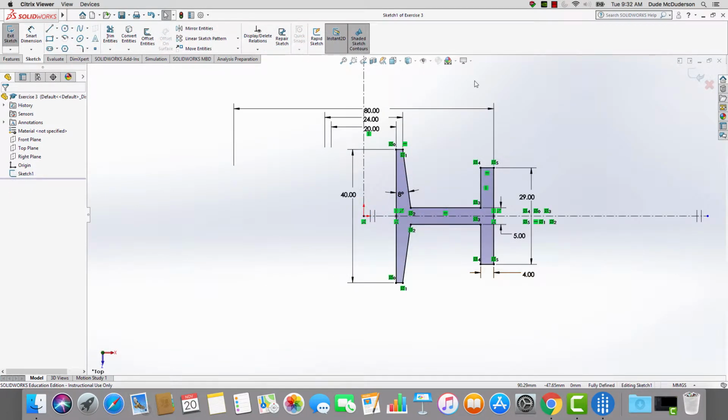So let's take a look at the sketch that underlies this revolve. Again, we're looking now at the cross section of the wheel, and we're looking at just one side of that cross section. Very much it looks just like this outside geometry that we've portrayed here. You'll note two other really important components here: the center line here, which is going to provide our axis of revolution, and we also have a center line here. This really speaks to efficiency in drawing. There's no reason to draw the entire thing when we can just draw this top half and mirror it about that line. We set these up at the very start of our sketch, and you'll see that as we go through this step by step. Outside of that, there are a lot of dimensions that make this up. They're all pretty straightforward and pretty easy.